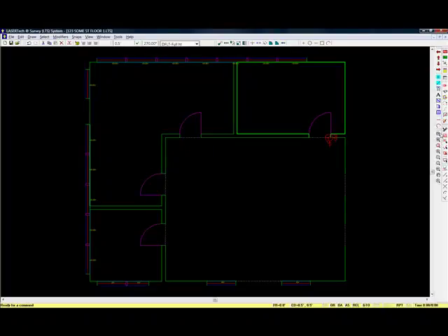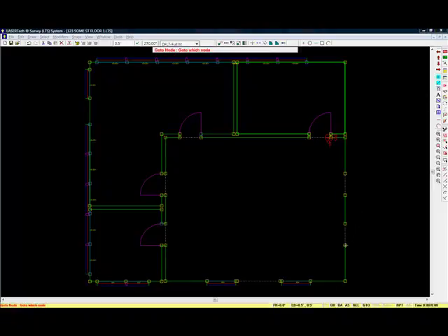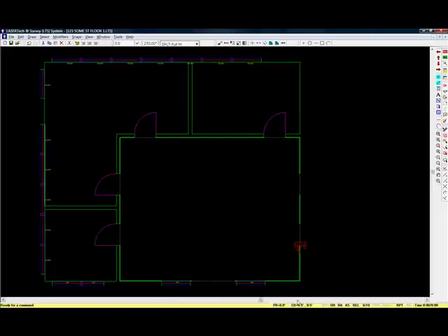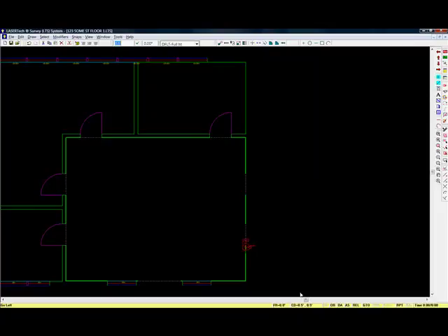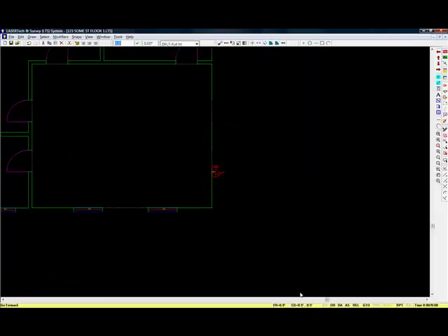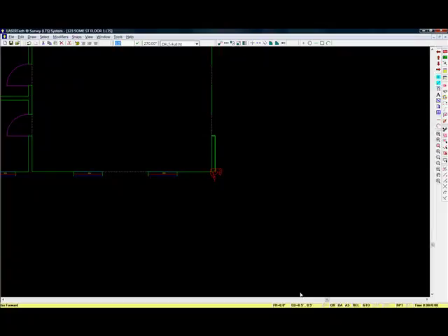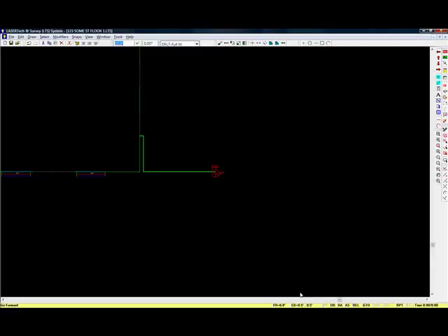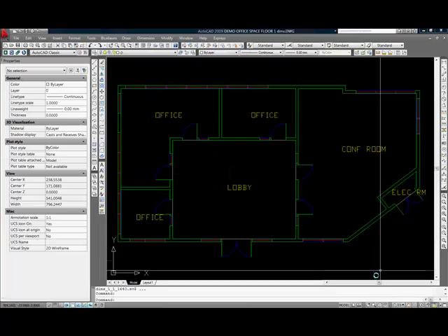So we're going to start down here. We're going to do a go to again. We'll go to this point, and I'm just going to scroll over a little bit, and we're going to turn, go 0.5, and then we'll come down 5 feet, and we'll turn left, and we'll go 9.9. Let's make it 10. Now we have this angled line here.